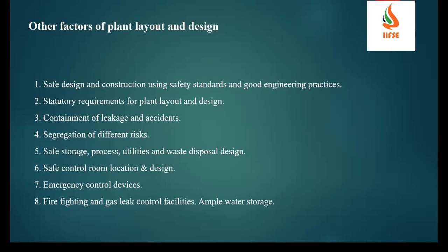If 100 people are there, 4 toilets need to be provided. If it is more, for every 50 we have to increase the number of toilets. Like that, whatever statutory requirements are required should be incorporated in the layout as well as in the design. And we have to check all of these when we design. Whatever legal requirements are there, we should plan all of them at the layout design stage itself.